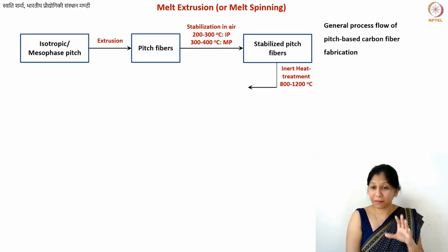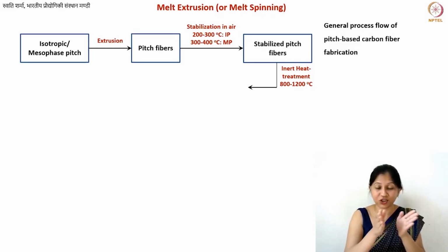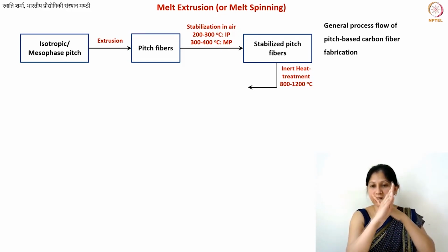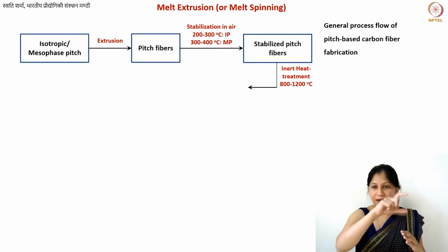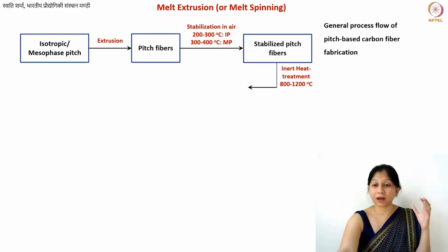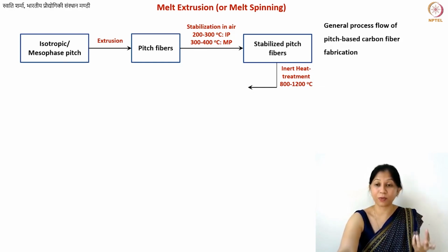But although they may have different kinds of structural arrangements, these graphite sheets may not be as nicely, you don't imagine these polycrystalline materials that I have shown, with random orientation. That is a possibility, but that is not the only possible microstructure. So we are also going to discuss what are the possible ordering, what kind of stacking of sheets that you get in these graphitic fibers. But that is only from the mesophase pitch. You can also get isotropic carbon from isotropic pitch.